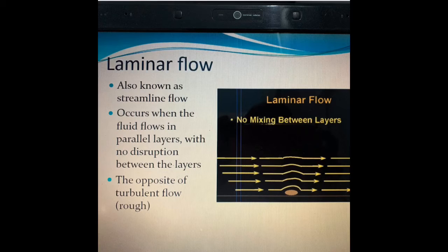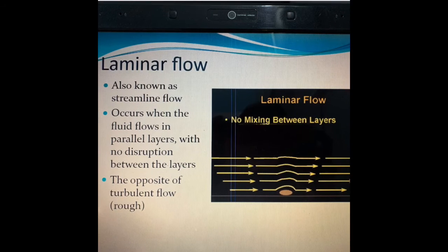The inclusion of viscosity also allows the possibility of two physically different flow regimes. The effect of viscosity on the velocity profile also renders invalid the assumption of uniform velocity distribution. Although the Euler equations may be altered to include shear stresses of a real fluid, the result is a set of partial differential equations to which no general solution is known. And laminar flow occurs when there is no disruption, that means when there is no obstruction, then only laminar flow can occur.